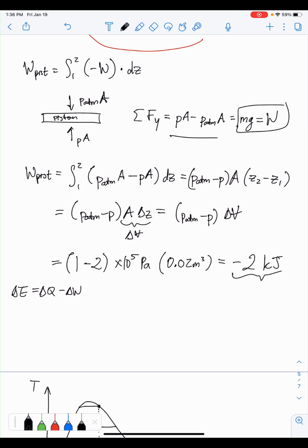Okay? And actually, speaking of this equation, let's break it down in order to find the change in potential energy. So at least for the time being, total energy can be broken down into kinetic energy, potential energy, and change in internal energy. So we know that, at least from the problem statement, if you read it, the gas takes in all the heat that's being input into the system. The piston doesn't receive any of the heat. So there's no heat transfer being done for the piston.